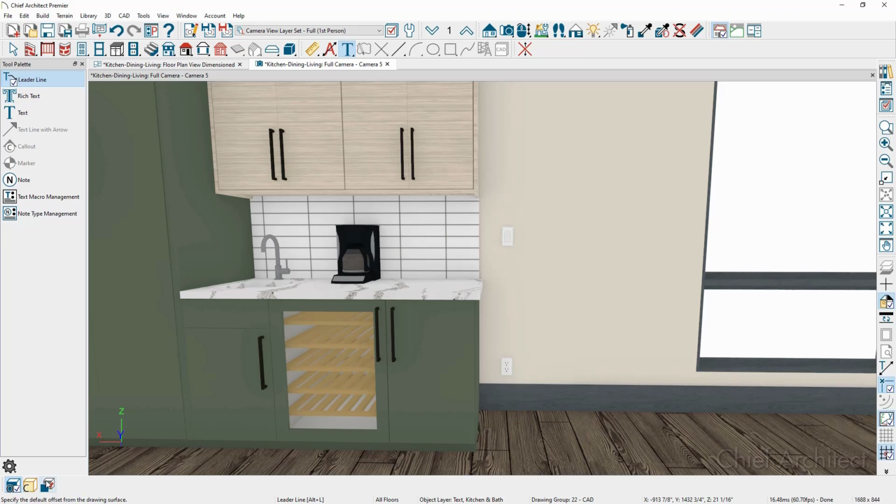And then one other comment here is that there's this option that says Set Offset. When you click on this, it lets you determine how far offset from the position that you clicked your text will get added. I'm going to go ahead and adjust this to 0 so that it adds directly on the face of the switch, and then click on OK. And then with my leader line tool selected, come over to the switch. We can see that I have the vertical face of the switch,